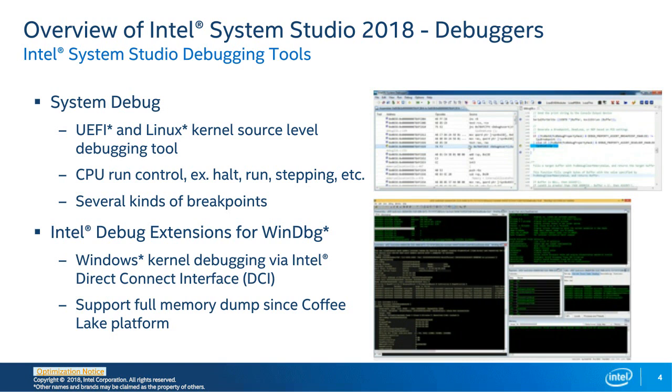When Intel customers start a new design and try to enable it, they may face a bunch of issues. If the issues happen in the BIOS boot up phase, System Debug can help to narrow down the root cause. Maybe the process is stuck in a while loop, or maybe something's wrong when loading EFI modules. The user can hold the CPU, check the source code, and track the instructions step by step with System Debug. More than that, System Debug has other useful features. You can find them in the how-to videos after the webinar.